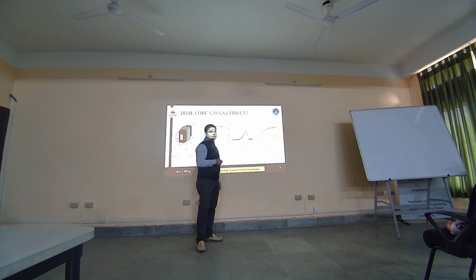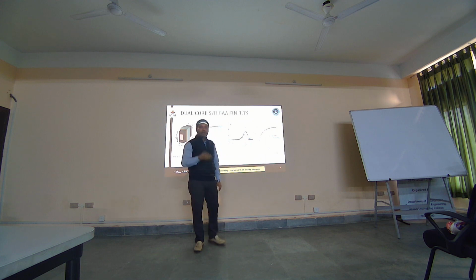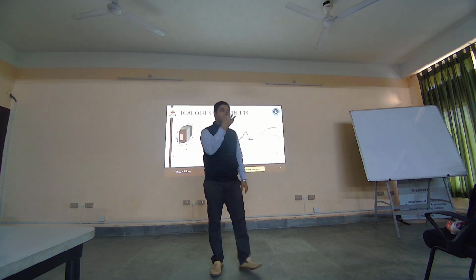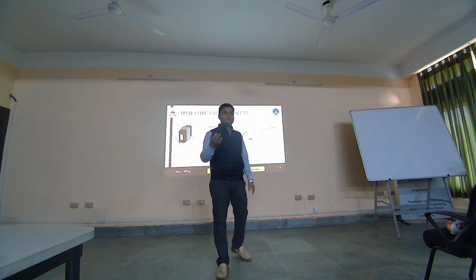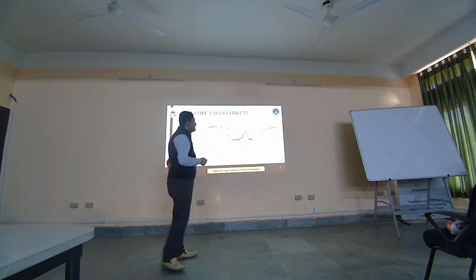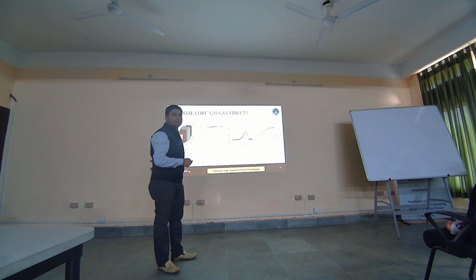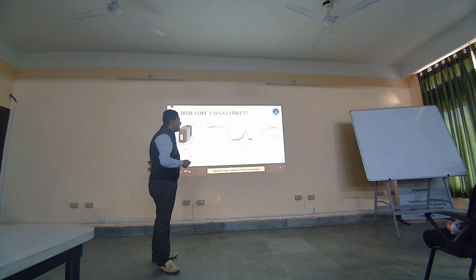One more important thing: for MOS based devices, you will always get this kind of very perfect calibrated curves in industrial simulators. Wherever there are MOSFET based operation devices which work on MOSFET principles, like FinFETs, MOSFETs or vertical FETs, there is a high possibility of getting such beautiful matching between simulation and experiment. But wherever there are other non-conventional models like TFETs, then you will have some kind of mismatch between simulated and your experiment during the calibration. Okay, and that is very well established.